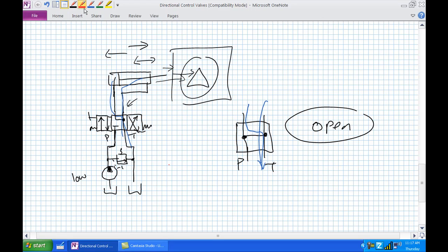And additionally, what's that pressurized flow going to? Well, it's dumping back to the tank at the low pressures of the tank. The relief valve does not need to activate. Okay? So what's the advantage of this one? Well, again, it's a little bit more efficient. You are not dumping at incredibly high pressures. Your pump is not working as hard. You can manually position this actuator.